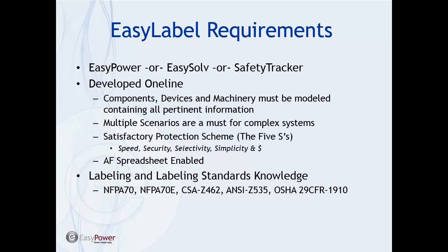So the arc flash spreadsheet is also a requirement. You have to have that enabled in the software. I'll show you how to get that going in a second. And then of course labeling standards and knowledge are always helpful: NFPA 70, 70E, CSA Z462, ANSI Z535, and OSHA.